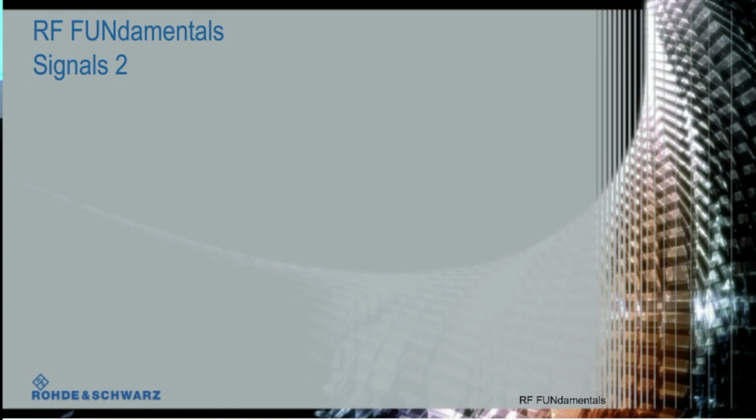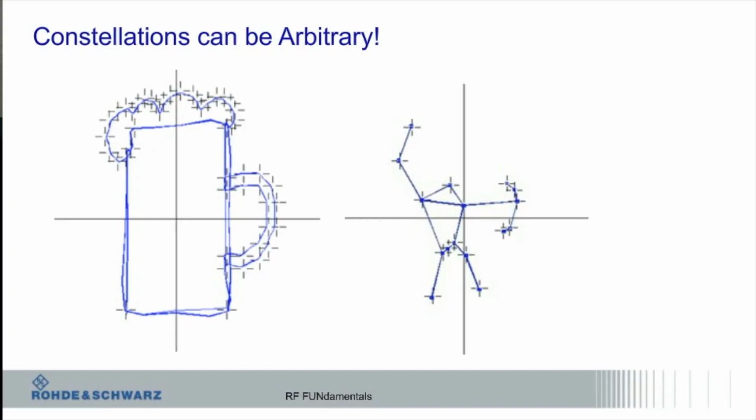Okay, so the first thing is, if you were measuring a VCO, which is probably the worst case scenario of that problem, whatever voltage the tune voltage is seeing determines what the frequency is, right? And if you had a crummy control voltage, that thing's going to move all over the place, obviously. So in that case, we actually have a tool for measuring a VCO. We have a voltage source on the phase noise analyzer itself, which will be able to track that. So that's one case.